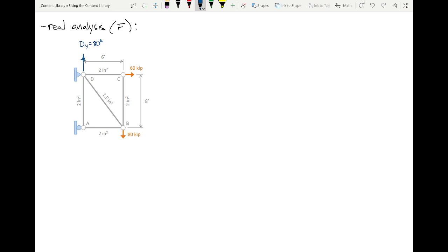So what I'm going to do, I'm going to be formal about it. I'm going to sum moments at A. Or sorry, no, sum moments at D. I meant sum moments at D. So if I sum moments at D, do I have to consider Dy? Do I have to consider the 60 kips? Do I have to consider the 80 kips? You bet. 80 kips times what moment arm?